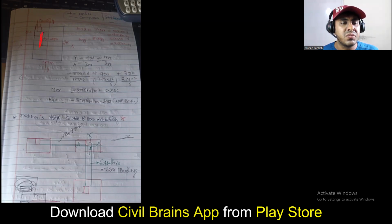This is the eccentricity. So here the calculation is mxx is equal to p into exx. P is 500. So 500 into 0.8 we have done. So this is your exx. See, your x axis is here. About that, in a perpendicular direction, you have to take the eccentricity. So this is your 0.8. So this is your mxx what we have taken. 500 into 0.8, you'll get 400 kilonewton meter.